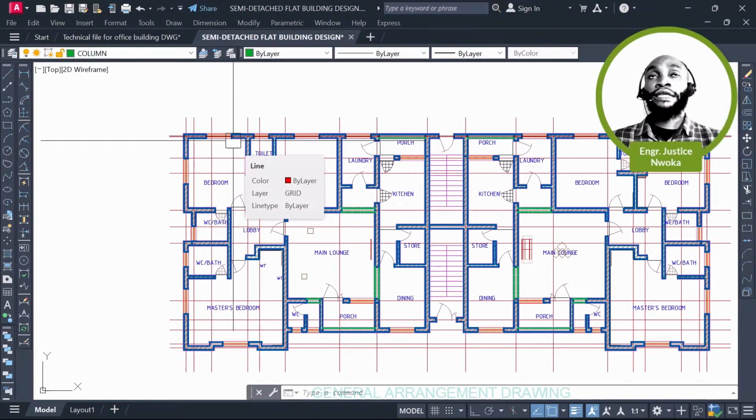But for this design right now, for a normal design, the most popular common shape of column that is used is a square column, or a rectangular column. But the square column is the first column shape that should come to your mind whenever you are performing the design of your structure. It is when it is not sufficient or when it fails that you can now go and choose a rectangular column.